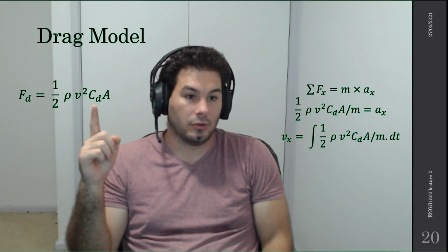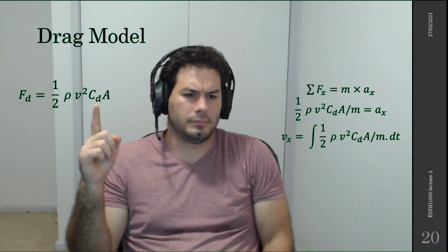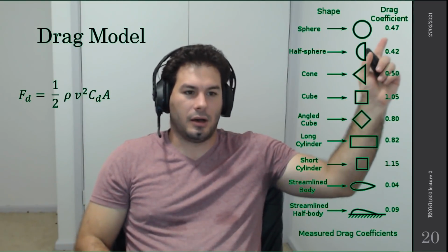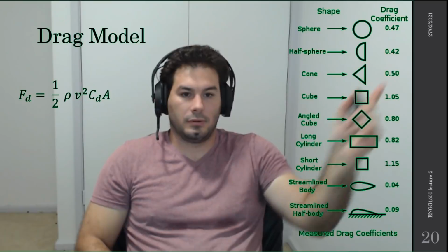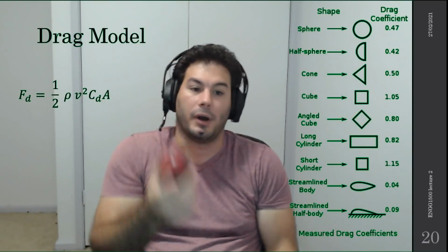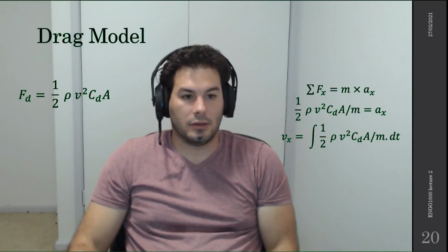It's about 1 kilogram per meter cubed. It's what you'll find if you look it up. Coefficient of drag, you can look up for a sphere, 0.47. And you have the area of your object, I'm assuming. You know your basketball, right? So you chuck that into the equation.